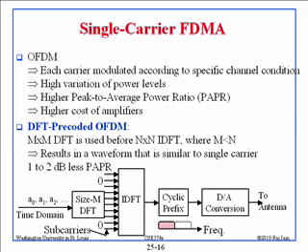Because of that, there is a big variance between the minimum and the maximum. There is a big difference between the peak and the average power, and that makes the amplifier design very difficult. I think we talked about this earlier, right? Peak to average power ratio. If you get an amplifier, by the way, it is the most expensive part in the whole system. So when you design a UE or a base station and you get the power list, part list, and cost list, the highest cost is the amplifier.